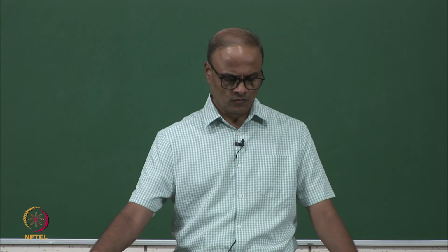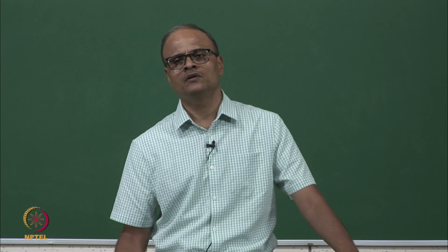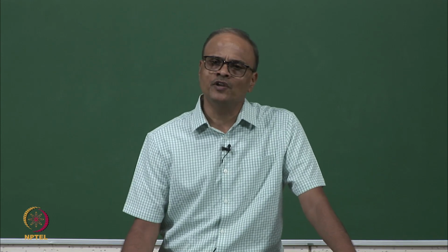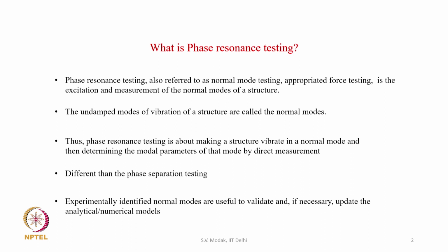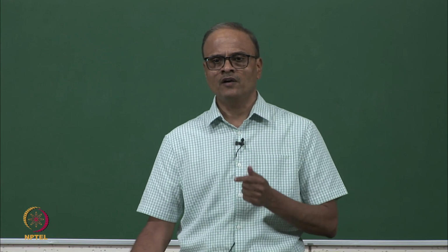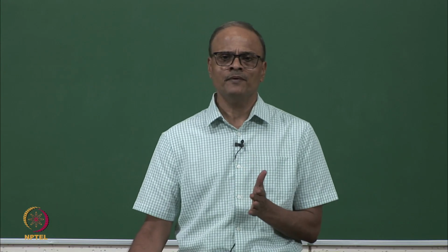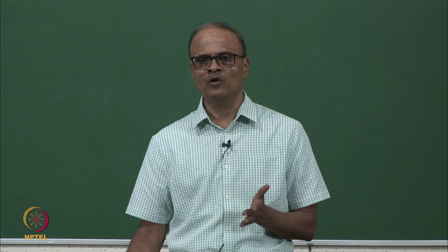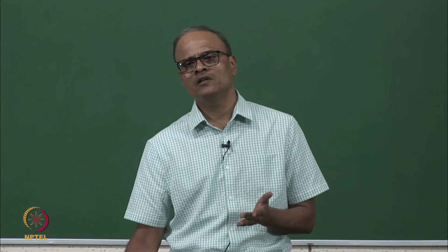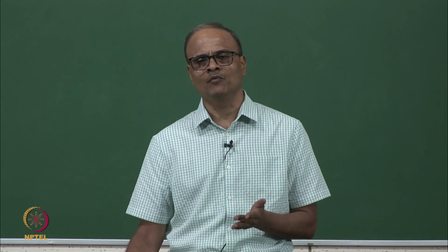Now why is it important to know the normal modes? Does it have any utility? The experimentally identified normal modes are useful to validate and if necessary update analytical and numerical models. The numerical models typically are finite element models. Finite element models generally either are undamped, that is damping is not modeled, or if the damping is modeled then it is based on a proportional damping model.